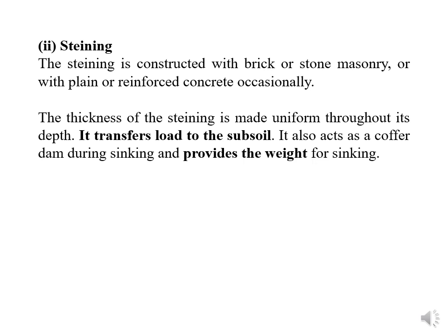Why is it required to make the thickness of the steining uniform? So that uniform sinking will take place, right? It transfers the load to the soil, the subsoil. It also acts as a coffer dam during sinking and provides the weight for sinking.